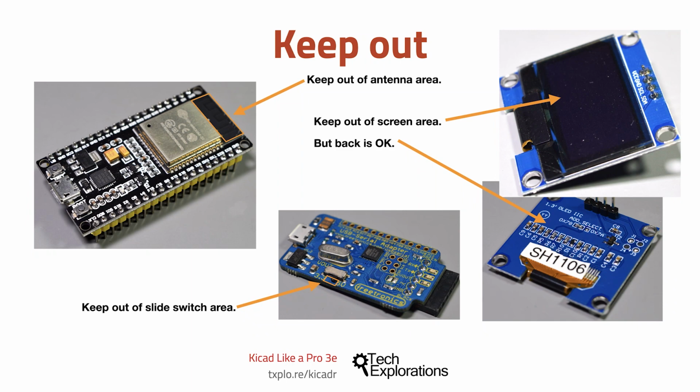In the last example, in the middle of the slide, is a UART interface with a voltage slide switch. The slide switch is oriented to its side, and even though the switch notch is very small, it is still a good idea to mark the area below it as a keep-out area, and I've done that with, again, the orange box superimposed on the photograph. This way, there is no risk of placing a footprint by mistake and obstructing the travel path of the notch.